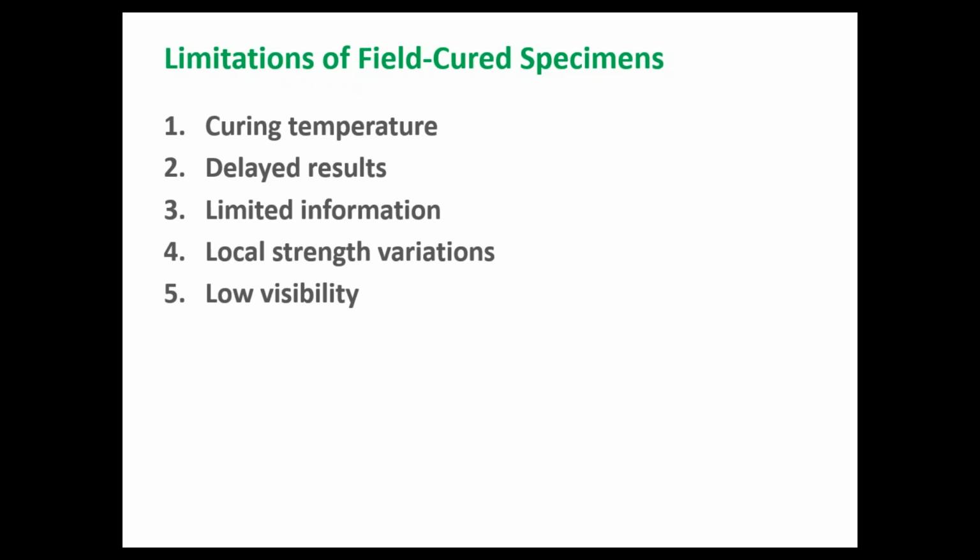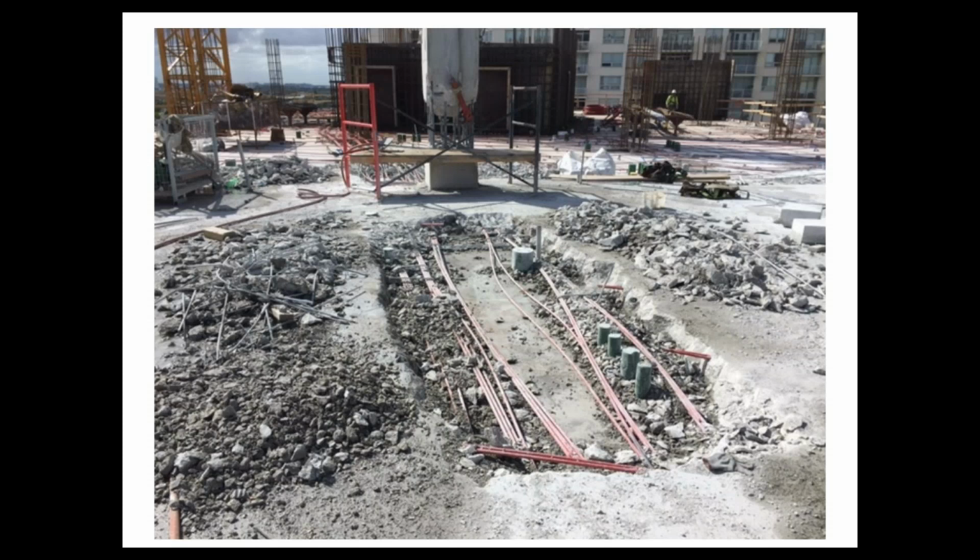Okay, and if you have a cylinder that doesn't really break well, this may end up to be the situation. This is actually a post-tension structure where the cables were pulled too early, and all the concrete cover was popped open. Again, this is showing that even if you have cylinders, not being able to capture the actual strength development inside the concrete can result in catastrophic damages.